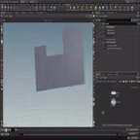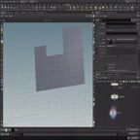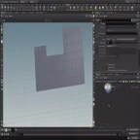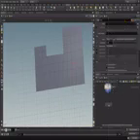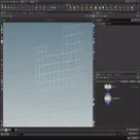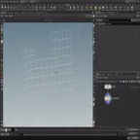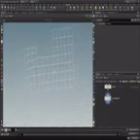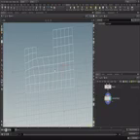Then place down a fuse node, because we do want them to be connected, not to be separate entities. And after that, a convert line. So we are heading towards the inside of the building layout generation. So for now, we're just going to make the main frame that we're going to use in the following tutorials to generate the layout. I'm going to show you some tricks to get certain patterns inside of the building layout generation, but yeah, there are just so many different layouts. You really need to know exactly what kind of building you're making before you can generate its layout.